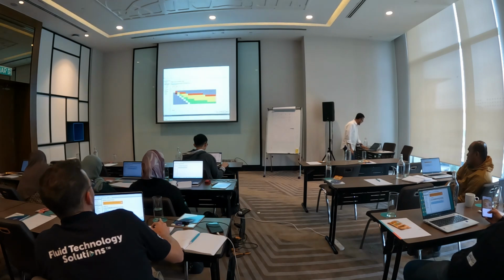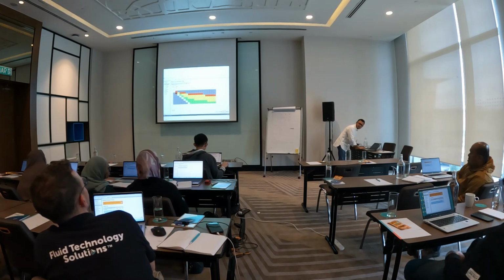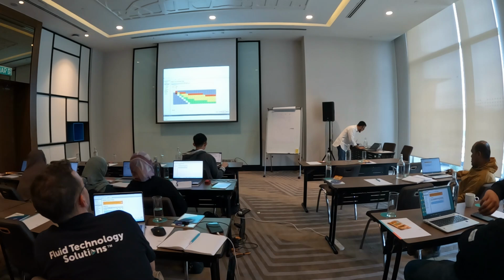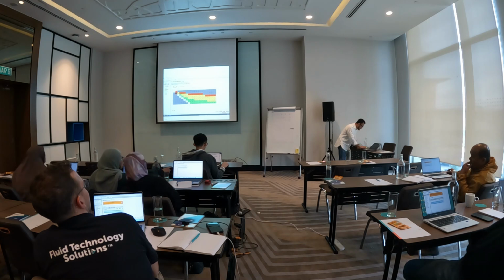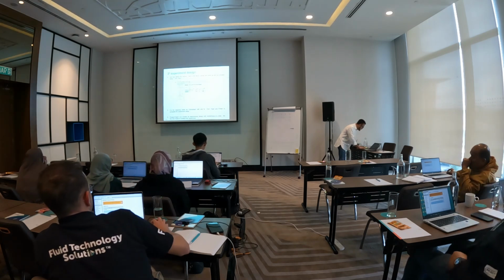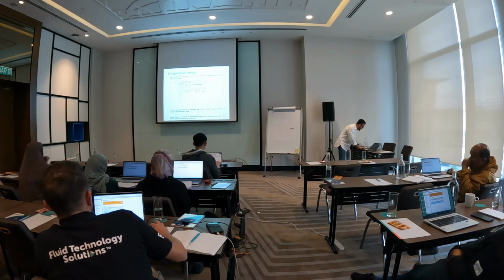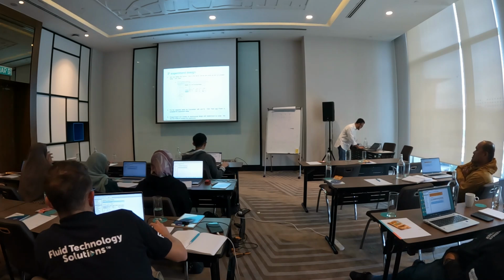Okay, this is very open, and then you can select regular level, 2 level, and select replicate because of replication, and then select this total count of 3 for full factorial, and then click next. Then you fill up all the info, change the temperature, pressure, and distance time, and then put low and high, 100 to 200, and also 6, and then click next and finish.